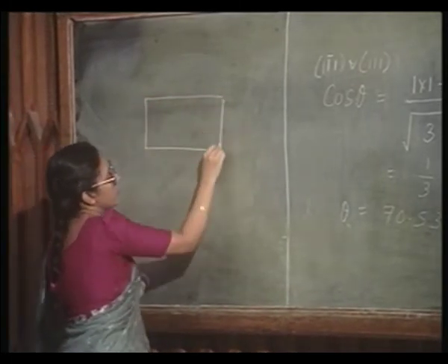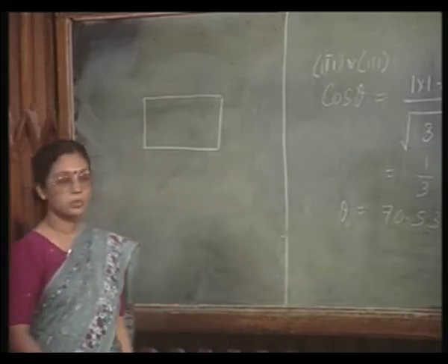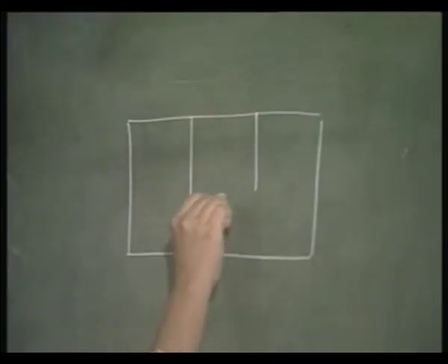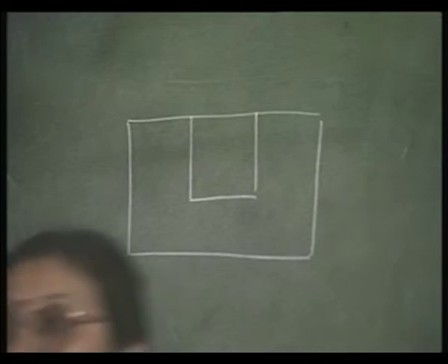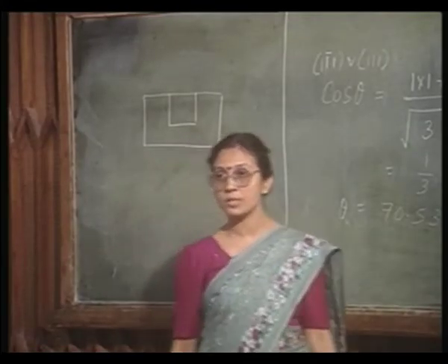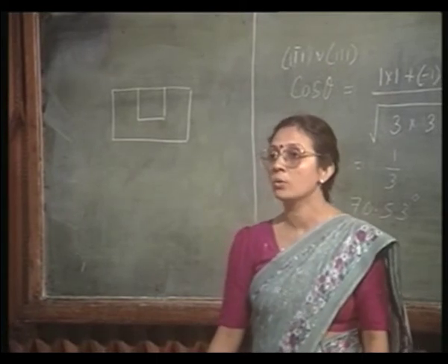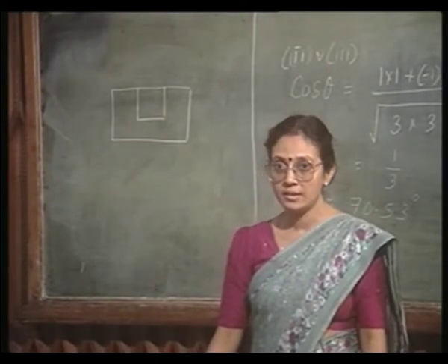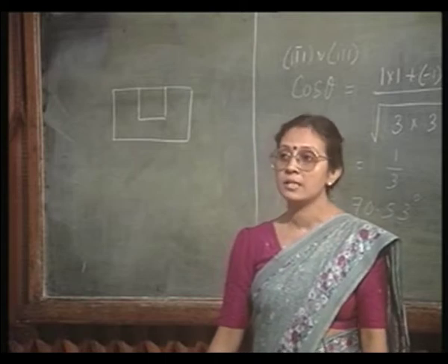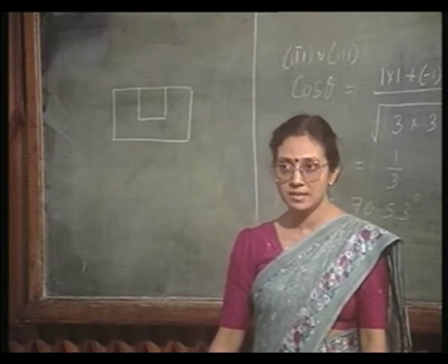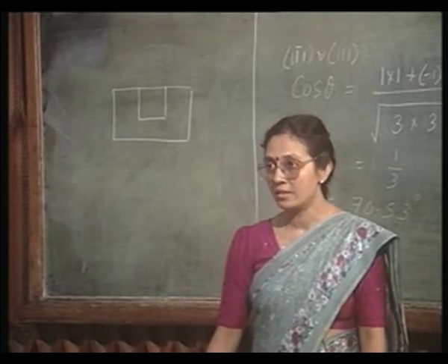if the surface is actually 110 and if you cleave, it is going to be like this. Or if you etch, for example, if you expose it to a selective etchant, the selective etchant is going to expose 111 planes and these 111 planes are going to meet the 110 planes at the surface at 90 degrees.